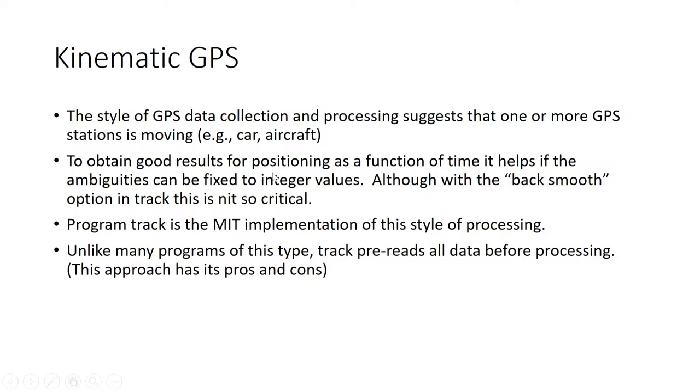And when you want kinematic GPS data processing, there is one module, the track module. When you use this track module, you can monitor a car or aircraft. If there is any co-seismic variation, like an earthquake has occurred, any volcanism has taken place, any glacier mass is moving, an avalanche is about to take place, or land subsidence is about to occur, all this motion can be monitored with the help of kinematic measurements, where you have to have a 1 hertz sampling interval. Then only this kinematic measurement is possible.